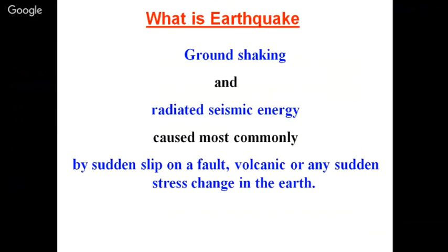What is an earthquake? As we all know, this is simply ground shaking having a focus which can be a few kilometers to hundreds of kilometers down in the earth's crust, and the energy travels simultaneously to the surface of the earth, giving the epicenter at the surface. In this type of ground shaking, we have some acceleration, and this radiates seismic energy, caused most commonly by sudden slip on a fault, volcanic activity, or any sudden stress change in the earth.